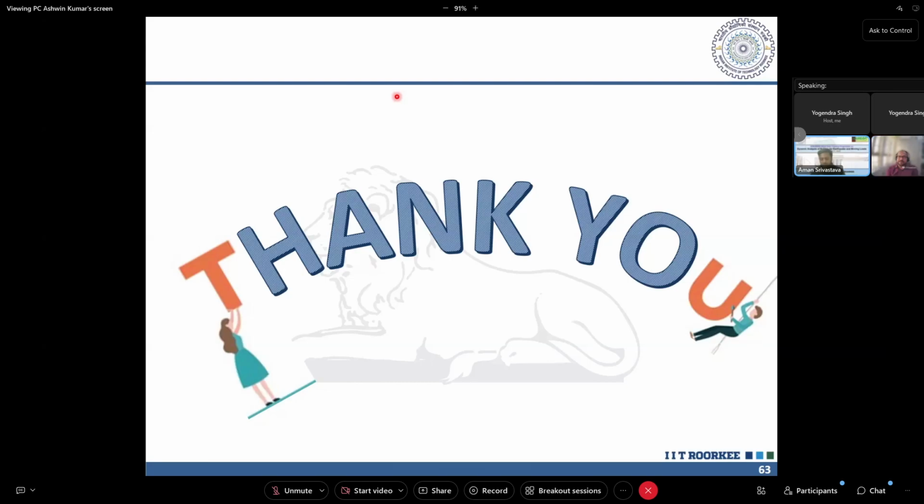Then there is a question from your previous, yesterday's presentation itself. Why do we call the time period and natural frequency of the first mode the fundamental time period? Because yesterday, when we arranged the frequencies in increasing order, omega 1, omega 2, omega 3, we got for omega 1 a mass participation of 90%, right? So the mode or the frequency which corresponds to the highest mass contribution is what we call the first fundamental mode, because it contributes the maximum amount of mass participation. So that is why I had written that particular thing. The rest are all natural frequencies of the system.